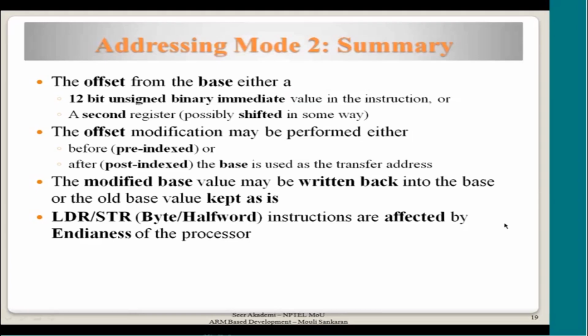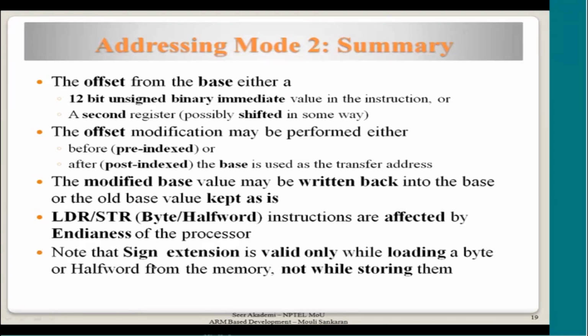Okay. So one more thing which I have not talked about so far: sign extension is valid only while loading a byte and not while storing them. This will be explained in the next session. But just suppose you are storing a byte value into the memory, you are interested in writing only one byte. Similarly, if you are loading a signed byte, that's what I am going to be explaining in the next lecture, immediately after this section.